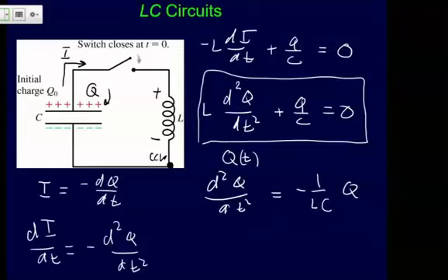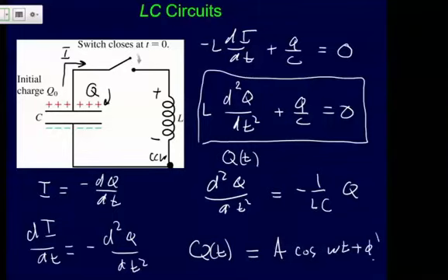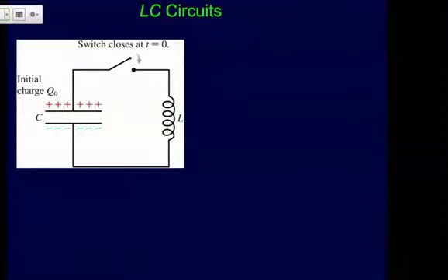Okay, so I'm hearing oscillating, sine, cosine. These are all correct, some sort of sinusoidal function. Now, what I'm going to do is make a general case. Our general solution can be written many ways, but I'll write it as cosine of omega t plus phi. These are all unknowns, and the way you do this is you solve for those unknowns using your initial conditions. But now, what does this mean for us? First of all, we're starting out at the time when Q is maximum.